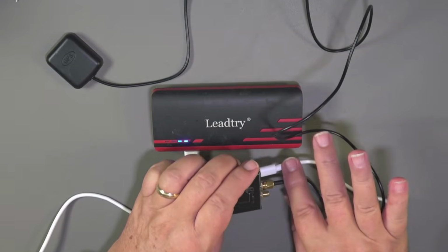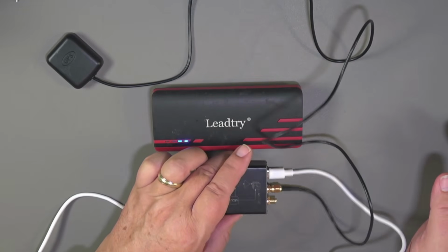Programming also occurs through the USB-C. That's a little different. We'll talk about that separately. As I mentioned in the clip, you'll likely need an SMA to whatever kind of coax connector you use. You can find these as part of assortments or get them individually. You'll need an SMA male to either BNC or SO239.